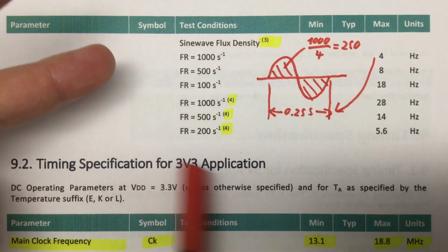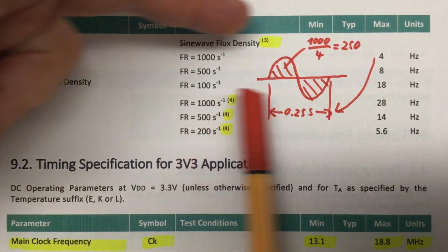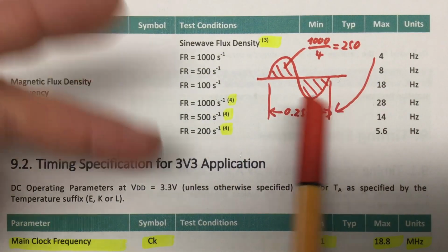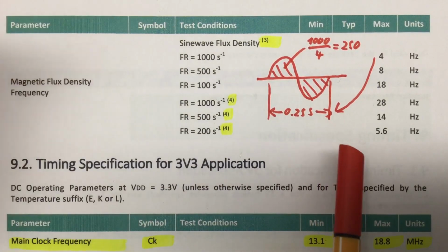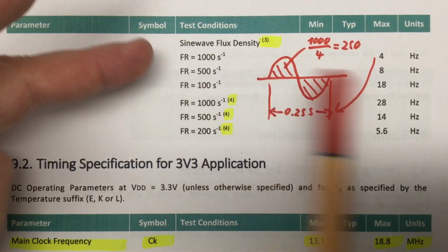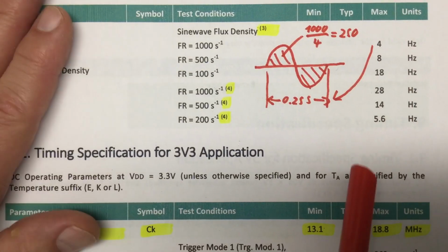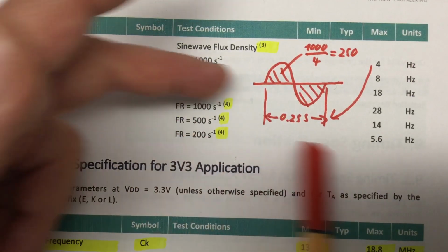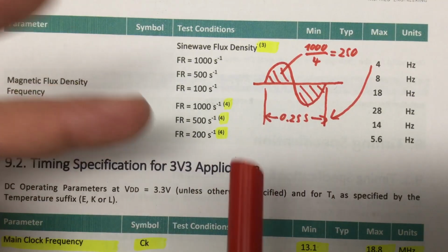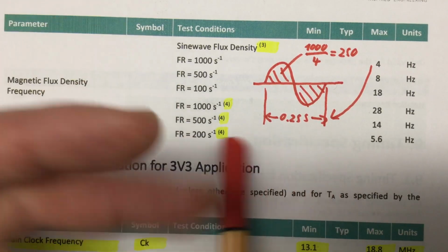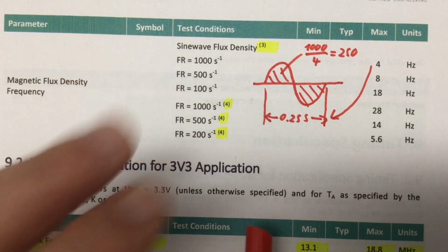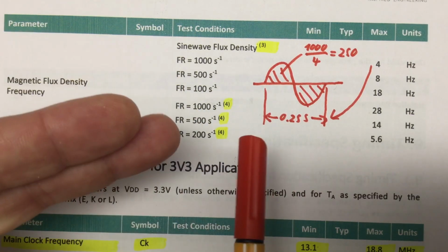So, interpreting this, the top 3 lines are the limits in regard to the sensitivity monitors when they are enabled. And you have to disable them when you go beyond these frequencies. The lower 3 lines are the limits linked to the automatic gain control, which you can also disable by setting max and min virtual gain to the same value.